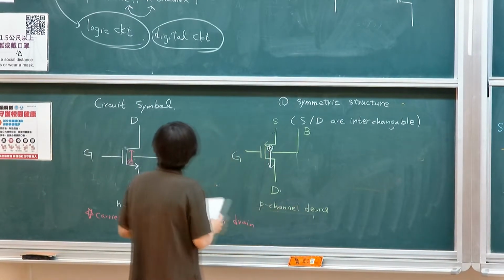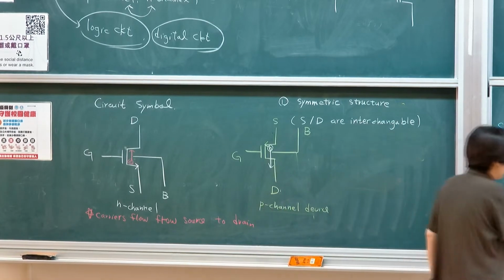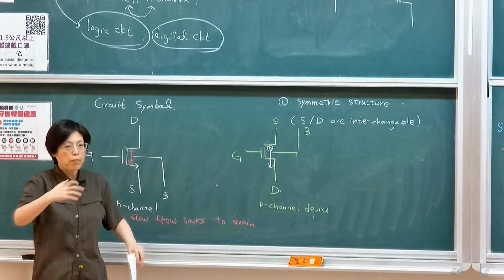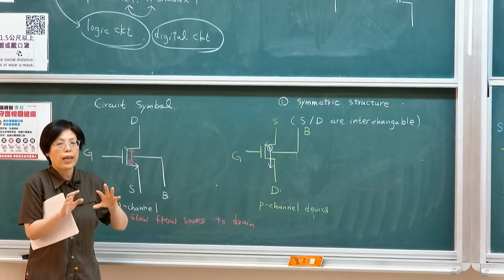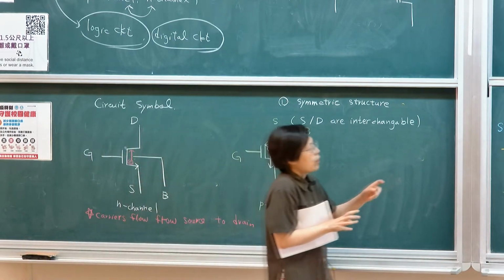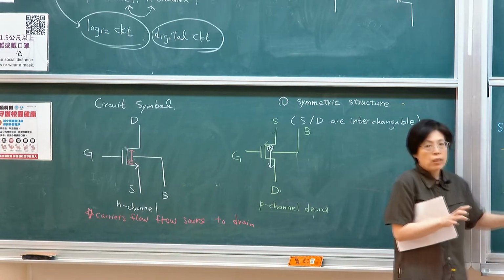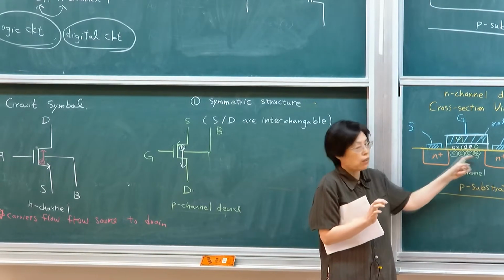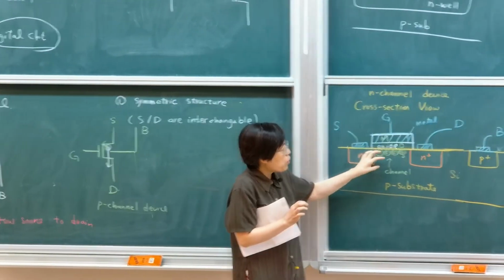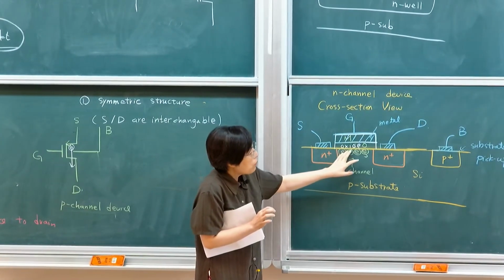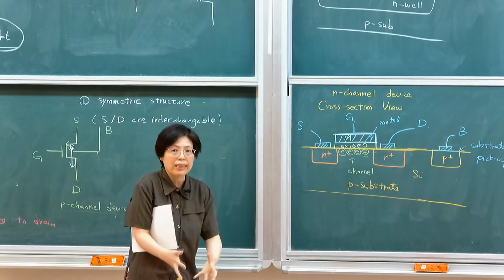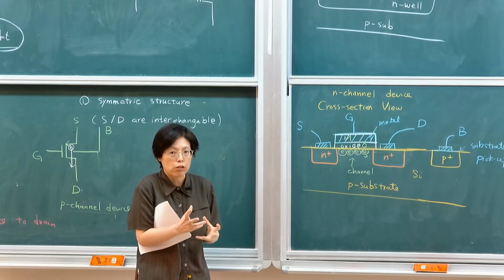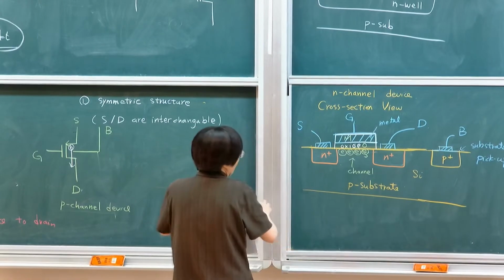Okay? So another thing I want to mention is that the main conduction mechanism of a MOS transistor is through whether there's a buildup of channel. So your main control is at the surface. This is called the silicon surface. What we want is mainly having the current flowing through the surface. We want to block anything under the surface, because the interface is the one being controlled. So what we want to do is to inhibit.